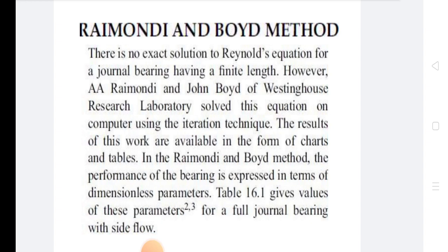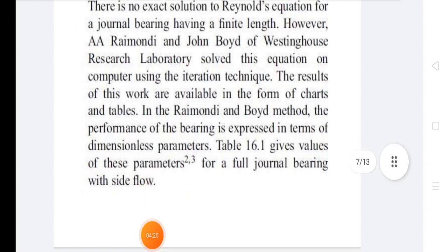The results of this work are available in the form of charts and tables. In the Raimondi and Boyd method, the performance of the bearing is expressed in terms of dimensionless parameters. The table gives values of these parameters for a full journal bearing with side flow.